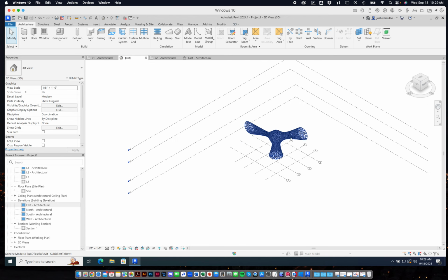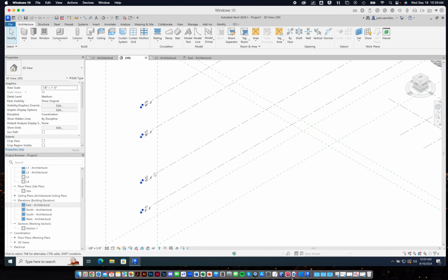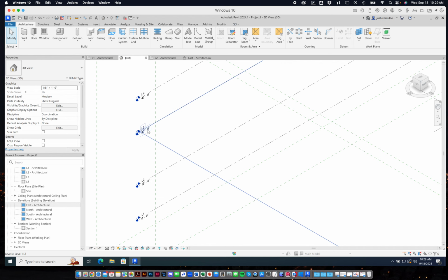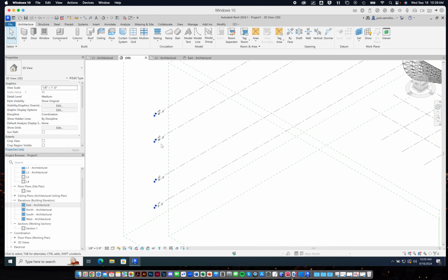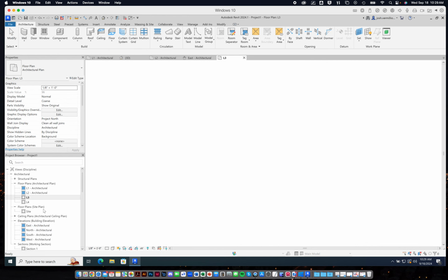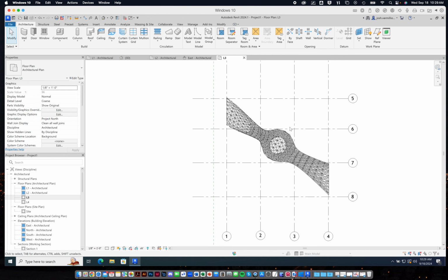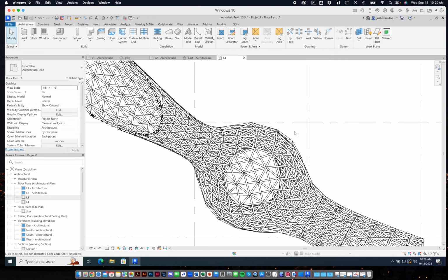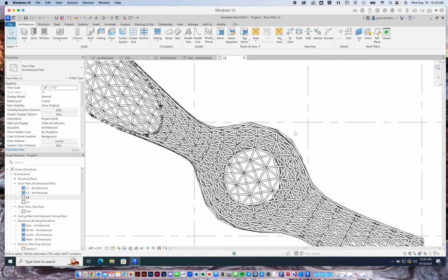Let's go to the 3D view. Yeah, and you can see, although the spacing's, well, no, this says 15, 30, I don't know what's going on there. Oh, I see. It's because this thing goes a little further. Anyway, you can see that we have these levels, right? As well. All right. So each time we add a level, we get another floor plan, right? So we have the floor plan at level 3. You can see each time it's cutting it wherever that level 3 is, 4 feet above it, using that cut plane, like a clipping plane, right? And then the last one, level 4.